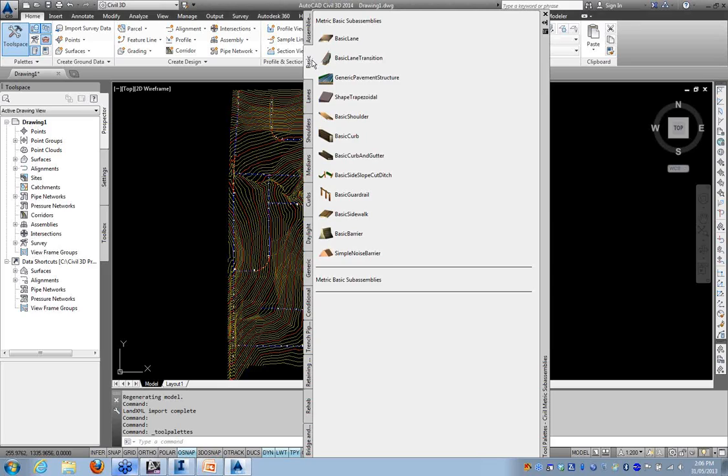Probably best to remove that tab completely. These are only supposed to be used for roughing out the design. If you start using these, and you go further down the track and want to get volumes and things out, you can't. And widening them and all sorts of stuff, it just doesn't happen. So I'd get rid of those basic ones, okay? So be careful with that.